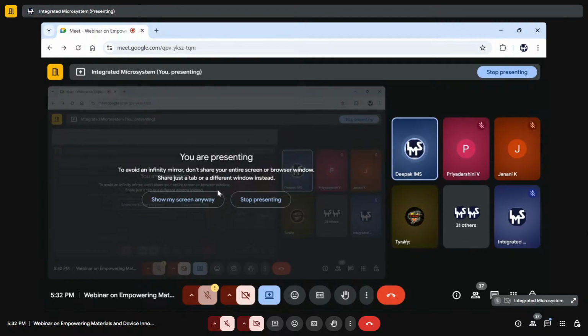In the plugin, while you were making this MoS2 nanotube, at that time you had selected molybdenum and sulfur and defined the bond length. Once you define the proper bond length between molybdenum and sulfur for MoS2, then you can create the MoS2 nanotube. But if you take a random bond distance, it will make a nanotube between molybdenum and sulfur only, not MoS2. So once you define the perfect value for the bond length, you can easily create a nanotube structure.